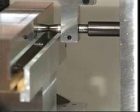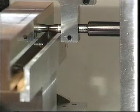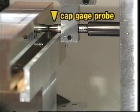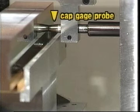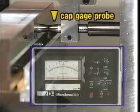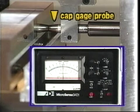The Z-motion error of the x-axis slide and the irregularities in the reference surface will be measured with the capacitance gauge. The non-contacting probe will sense changes in the distance between the probe tip and the straight edge by measuring capacitance changes between the target area on the reference surface and the probe's 1.7 millimeter diameter sensing area. The separation changes can be read from an analog display or can be expressed as an analog signal voltage.